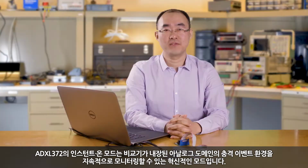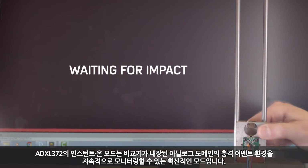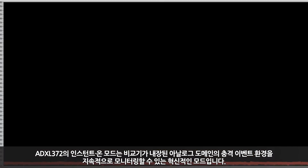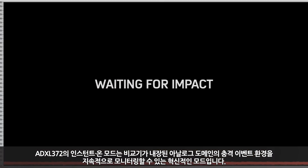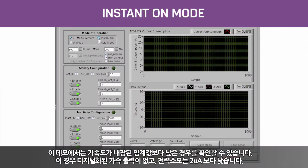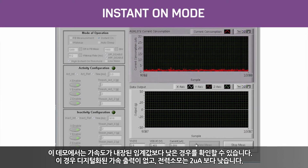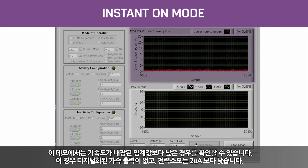The ADXL372 instant-on mode is an innovative mode that continuously monitors the environment for impact events in the analog domain with a built-in comparator. In the demo, we can see when the acceleration is lower than the built-in threshold, there is no digitized acceleration output, and the power consumption is lower than 2 microamps.